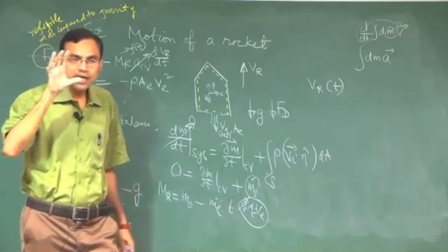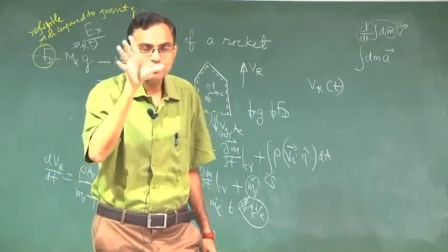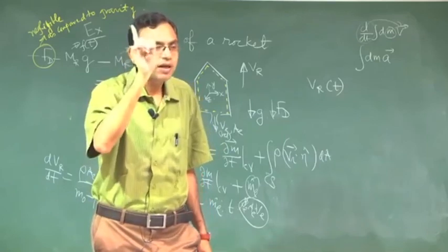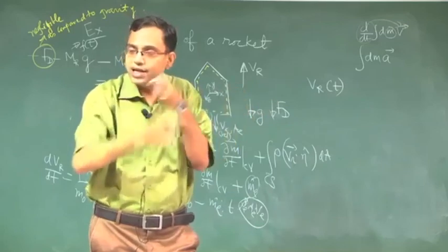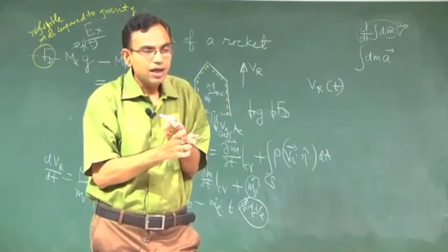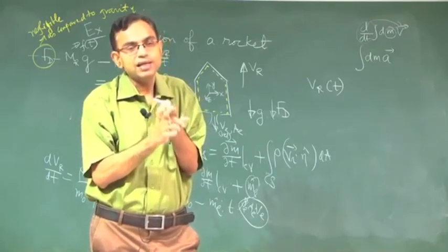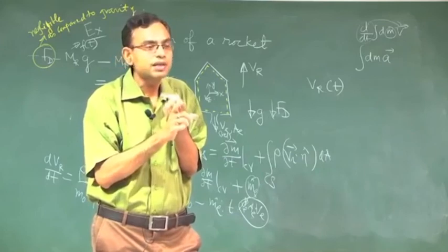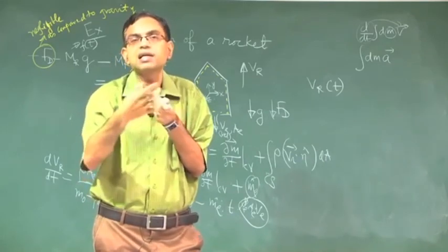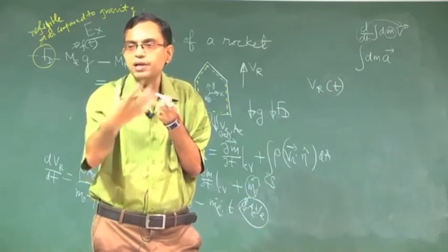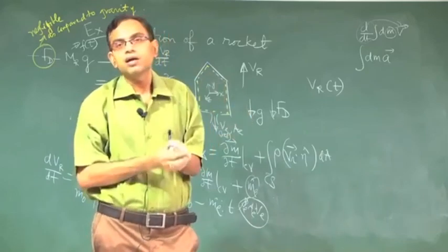So we can get rid of the situation again by freezing or snapping the phenomenon at a given instant of time when the system and control volume are merging. So instantaneously whatever is the mass at that instant, that is the mass within the control volume, as well as the mass of the control mass system that you can think of, and you can work with that instantaneous mass, assuming that in the limit as delta t tends to 0 your system and control volume converge.